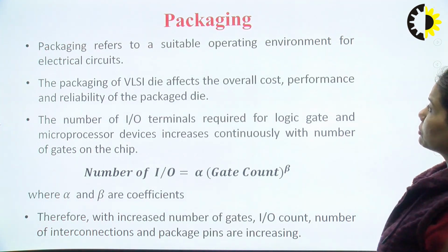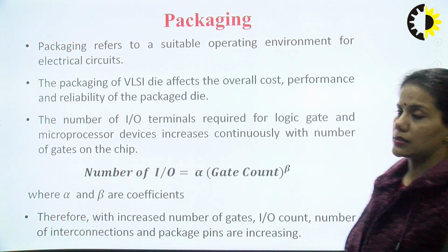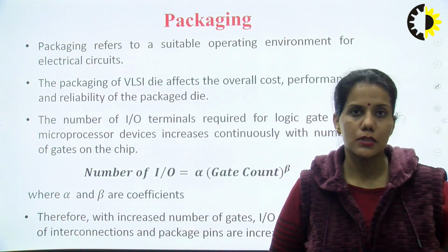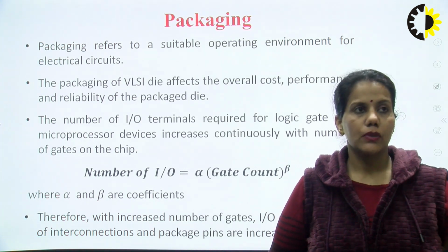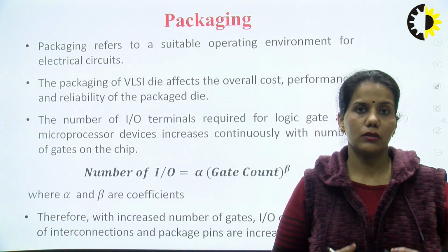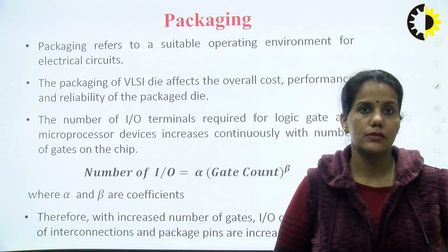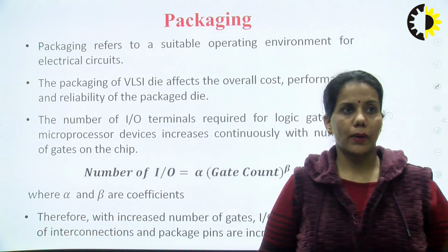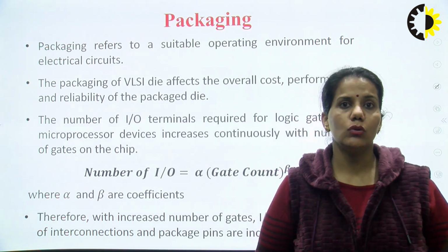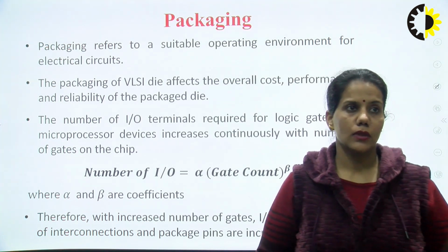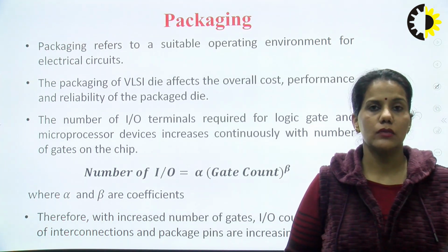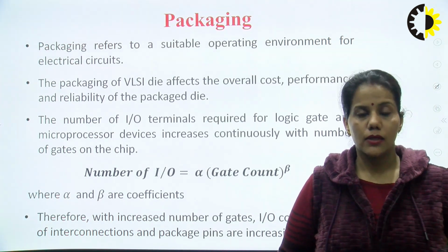Packaging refers to a suitable operating environment for electrical circuits. So we know that a chip is a combination of various pins and various interconnections, and we need to provide a suitable environment for every integrated circuit, that is every IC. So packaging basically refers to the environment that we are providing to an integrated circuit. The packaging of a VLSI die affects the overall cost, performance and reliability of the packaged die. How?